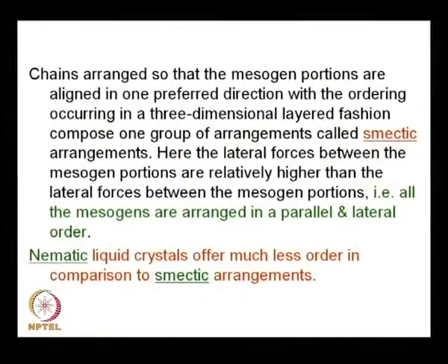Nematic liquid crystals offer much less order in comparison to smectic arrangements. That is why nematic LCPs are of lower viscosity than smectic LCPs. Very simple concept.